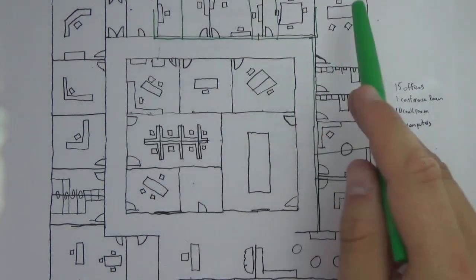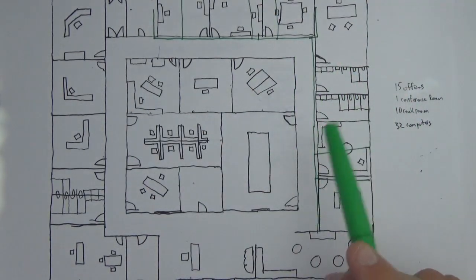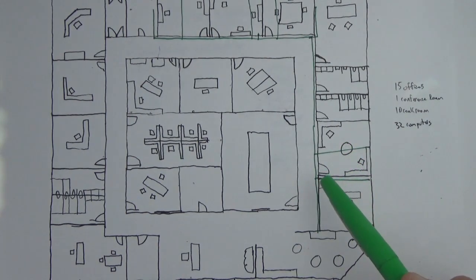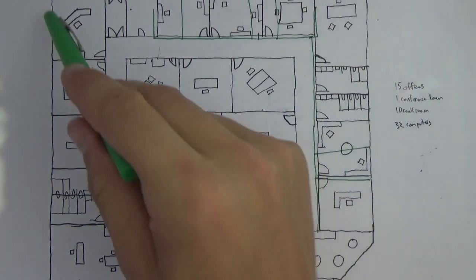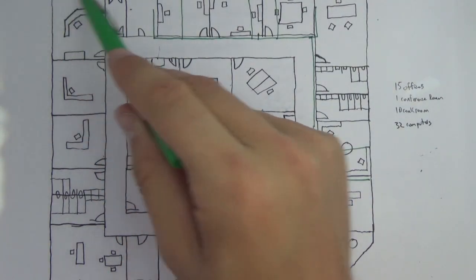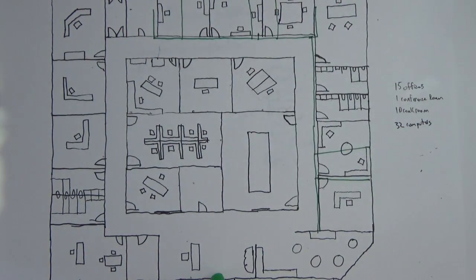All of these runs, based on the size of this building, are going to be far less than 90 meters, so we shouldn't run into that problem. But if you're working on a larger project, or you've got some ridiculous runs, like maybe our comm room has to be in the corner of this building, and we're trying to go all the way around the perimeter to get to a point over here, now that's going to get pretty close to our 90 meters. We need to be thinking about that.